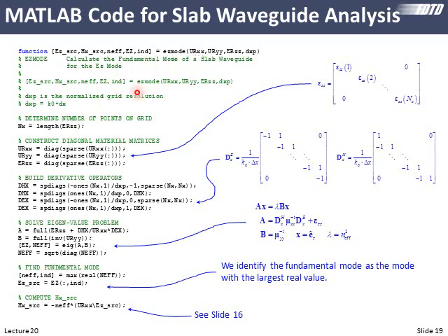The first thing we do is we look at how big our grid is in the x direction. So we just look at the length of one of those. We could have used any of the three, URXX, URYY, ERZZ. I was in the mood to choose ERZZ here. Then these come in as one-dimensional arrays because we extract them from our 2D grid in finite difference time domain. Remember, we need to diagonalize these. So we stick them into a diagonal matrix, and we also make that matrix sparse. What that does is it doesn't really store anything that's zeros. It just stores the non-zero elements. So this matrix takes up a whole lot less memory stored as sparse. Then we go ahead and build these derivative operators. Notice they really just have two dominant diagonals. So that's what's happening.